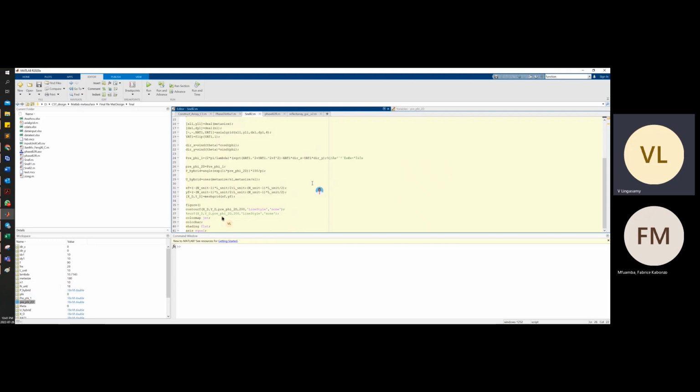Because it is minus 180 to plus 180, right? So 180 degrees we are getting. But the thing is, it is wrapping within plus 90 to minus 90. That is why you are getting that phase. So you have to unwrap that phase, then only you will get that. The second point is that the focal distance to unit cell distance should be appropriate, then you will get that phase.